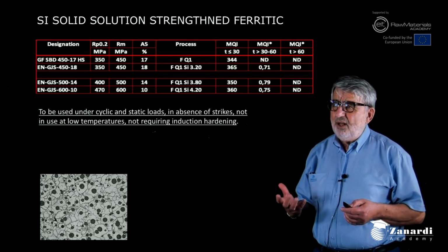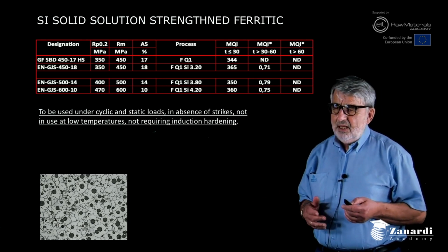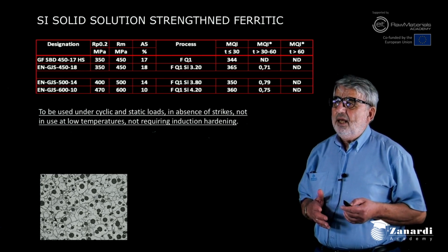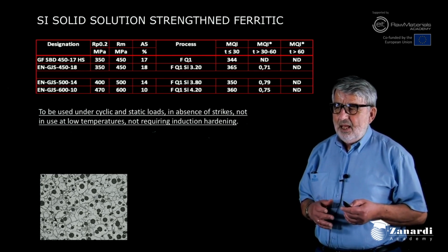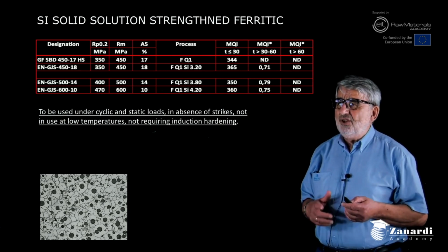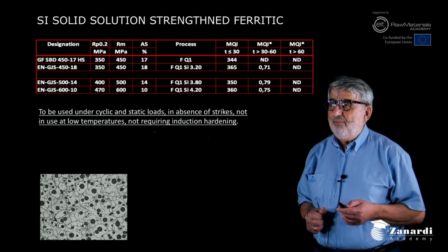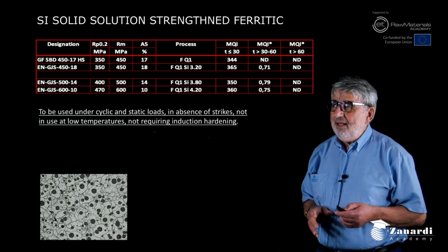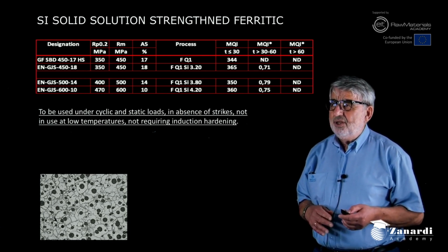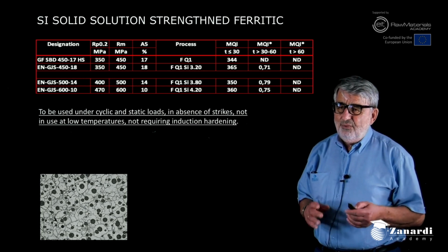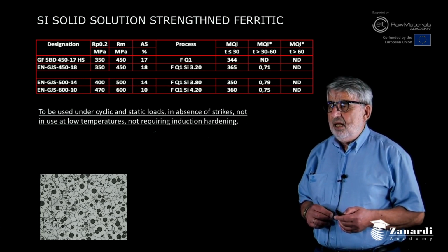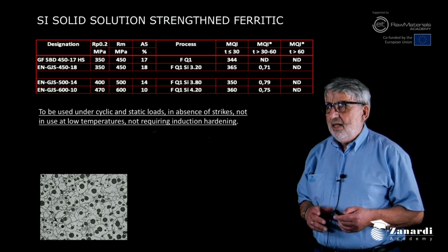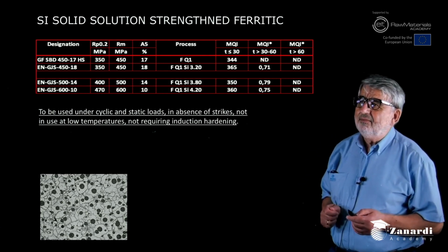that shows a very good combination of yield and elongation in uniaxial tensile test is a brittle material when triaxiality is pronounced, and needs to be approached very carefully with a very careful and responsible design.